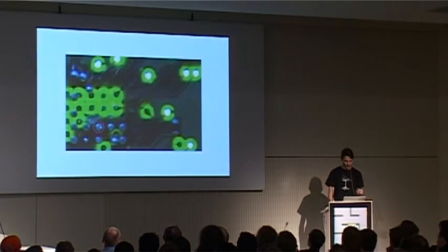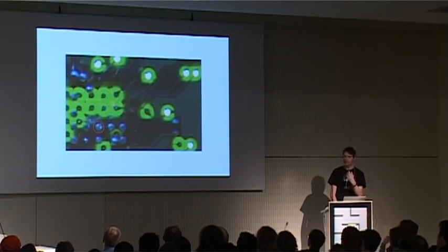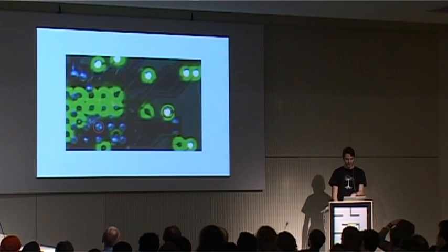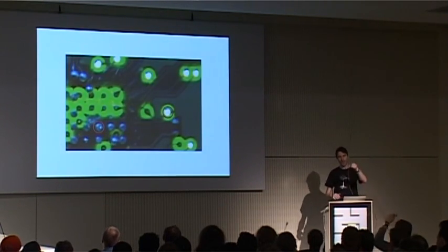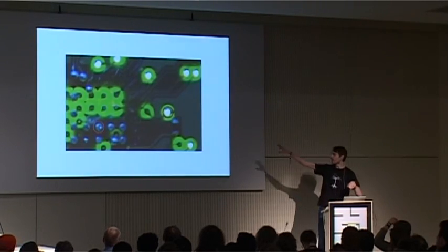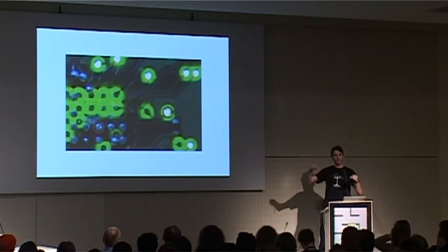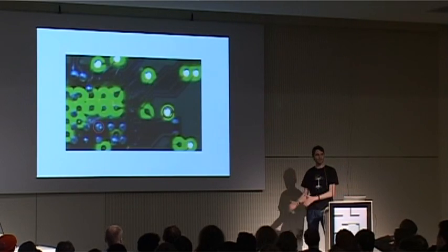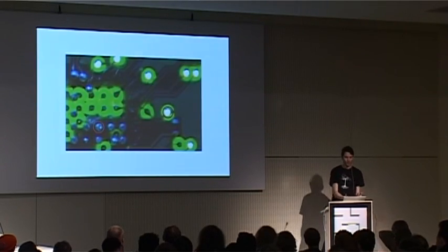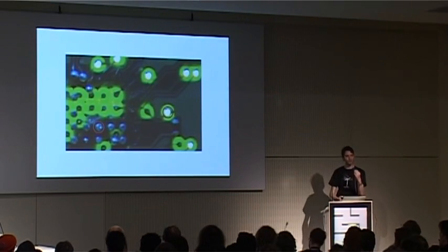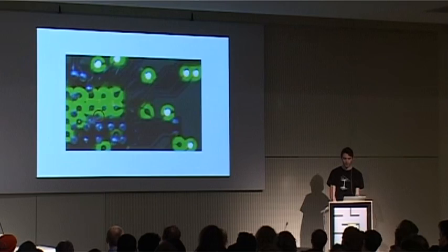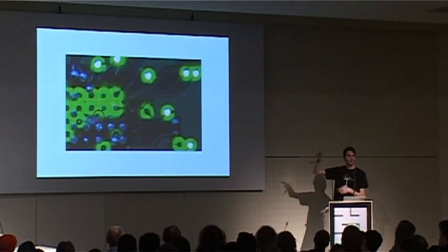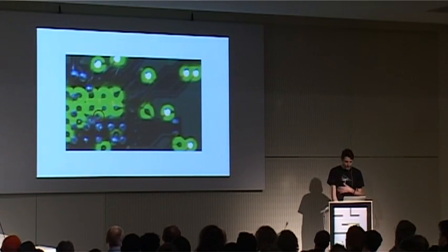If we zoom in a bit, we can see this is what a solder ball should look like if you properly remove the chip. What I would use that for is to tap onto the solder point and then find a via on the outside, such as the other one, and see if they connect. If they connect, and it's important, let's say it's a JTAG pin, then I would go to a device that I haven't destroyed and attach JTAG to it. In this particular case with this target, I had a footprint, and I knew exactly which pins were JTAG. The problem is that one of those pins, the ball was broken off, and there was no contact point left. So there was no way for me to map it out to the outside of the rest of the board. So we zoom in again.